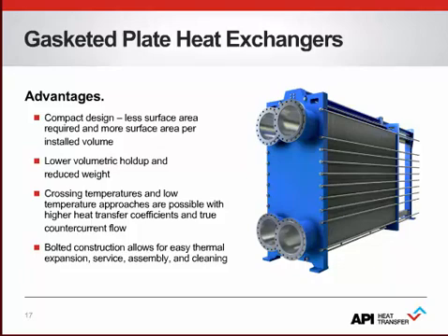Due to the strong countercurrent flow, it is also easily possible to have crossing temperature applications. It is possible to go down to only 1 Kelvin between the fluids. So you may have water from 6 to 12 degrees Celsius on one side, and on the other side you just cool down the hot water from 13 to 7 degrees Celsius. So a very close approach.